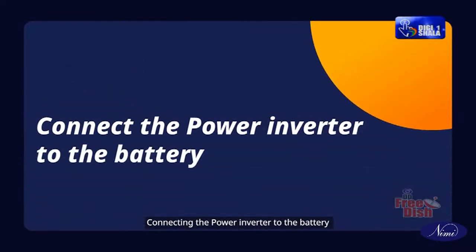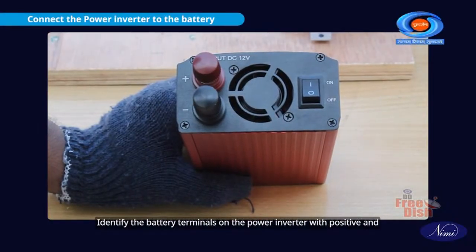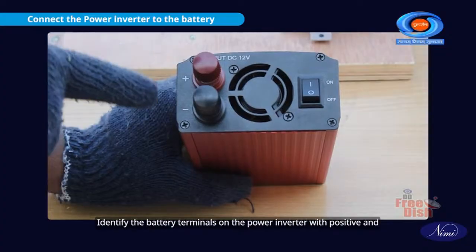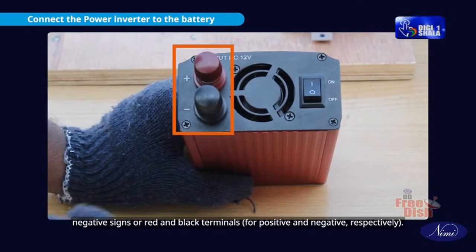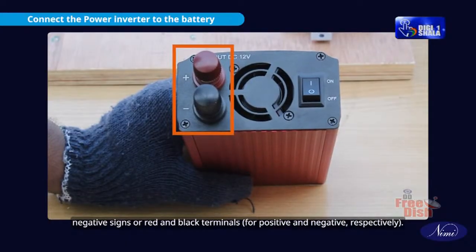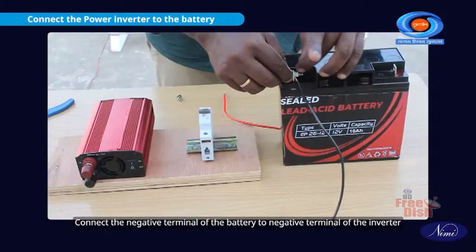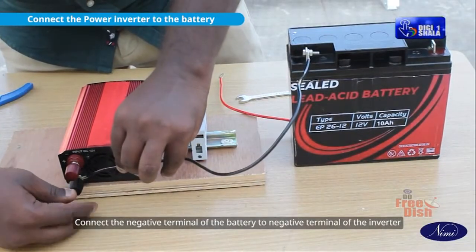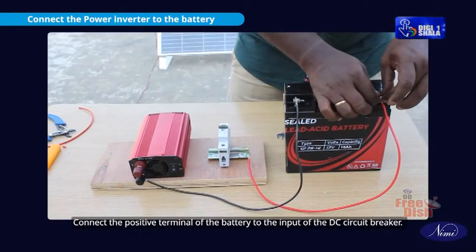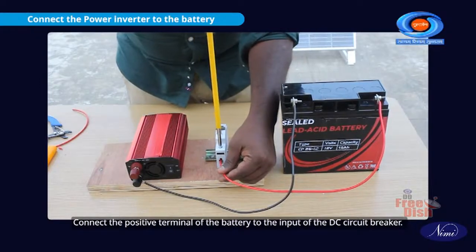Connecting the power inverter to the battery. Identify the battery terminals on the power inverter with positive and negative signs or red and black terminals for positive and negative respectively. Connect the negative terminal of the battery to the negative terminal of the inverter. Connect the positive terminal of the battery to the input of the DC circuit breaker.